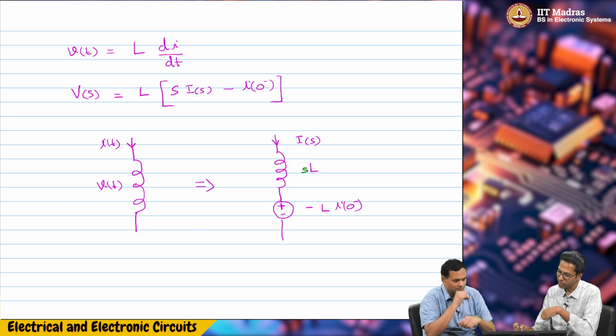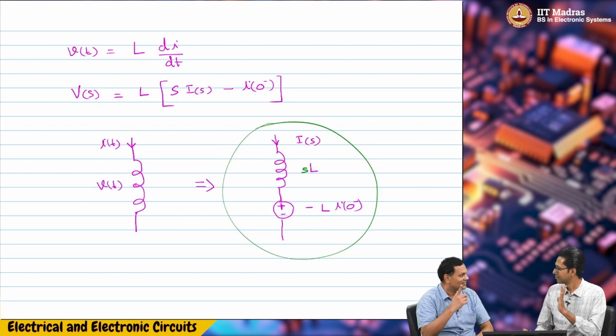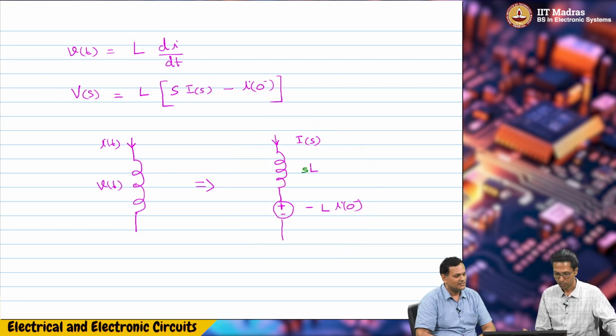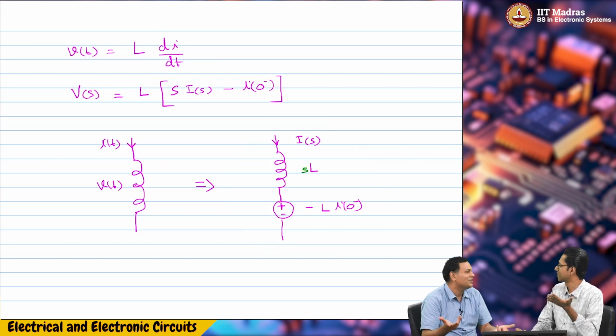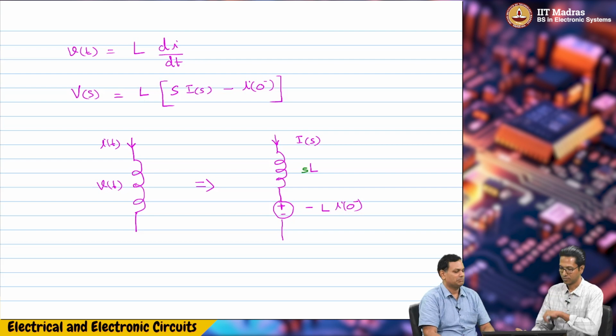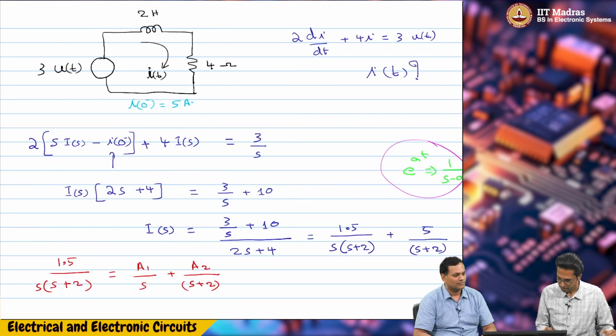So, shall we place this instead of our differential equation and just solve the equation directly? Okay, let's do that. For the resistor, there is no problem, there is no differentiation involved. So V of s will just be R times capital I of s. That's all. Let me copy the circuit, otherwise.